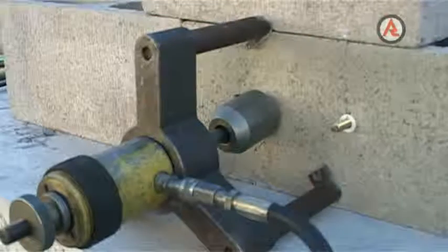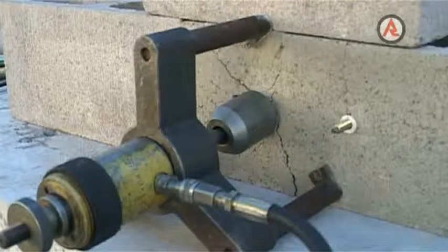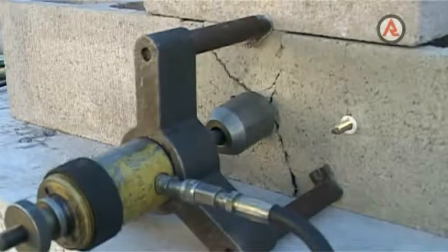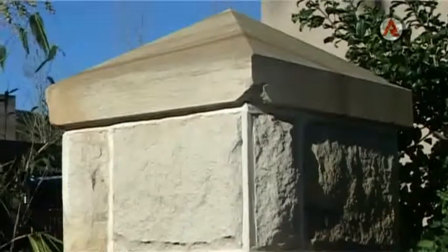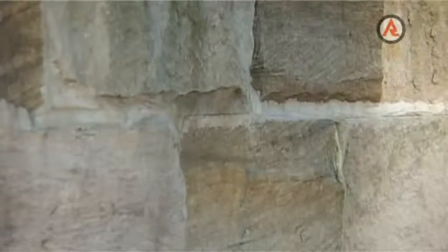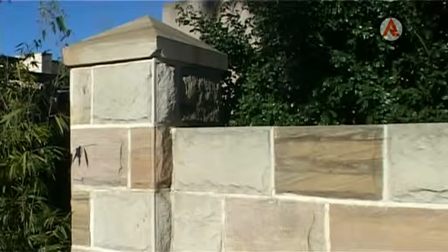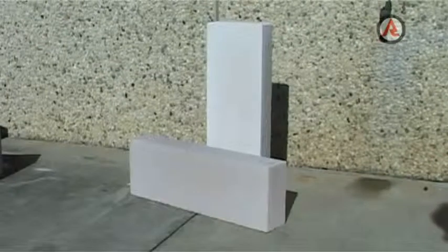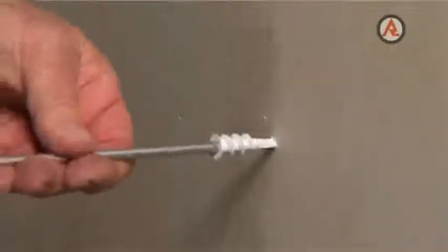The load which can be applied to a fastener in hollow brick or block may not depend on the strength of the fastener, but on the point at which the block disintegrates or pulls out of the wall. Natural stone comes in an almost endless variety, both in composition and strength. The success of fastening into stone will depend on the type of stone and also on the way in which the stonemason lays it. Other masonry materials in common use are lightweight aerated concrete and gypsum plasterboard.